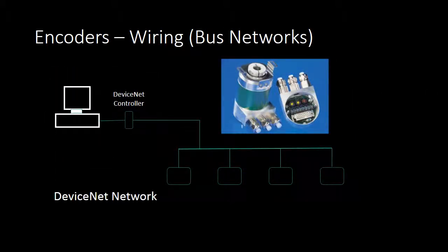Point-to-point serial protocols require 1 slave per master, while industrial buses allow multiple devices to be connected to one master. Addressing can be set using rotary or dip switches, or by software, and if the device is located at the end of the segment, an integrated terminating resistor can be activated. Common bus protocols include DeviceNet and Profibus.